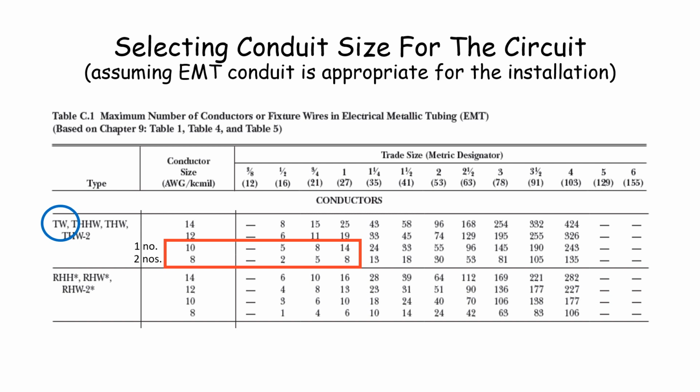But if we are going to use number 10 and number 8 here, we can never get the value of the conduit size. So let us assume instead of 2 number 8, since 8 is larger than 10, so let us make it 3. Let us make these 3 conductors number 8. So if you are using the table, we will use this 5 conductors because there are only 3. If we use 2 here, it is not sufficient, it is not possible, so we will use 5 value here, and this corresponds to 3/4 inch conduit or raceway, which is equivalent to 21 mm diameter.